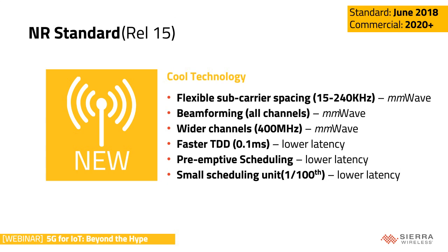It's arguably the most important difference between LTE and NR. So LTE has this fixed subcarrier spacing, and this is for the OFDM modulation, where NR now supports a variable subcarrier spacing between 15 and 240 kilohertz. The higher subcarrier spacings are absolutely mandatory if we want to support that high spectrum, especially the millimeter wave. This is why LTE simply can never run in millimeter wave spectrum.